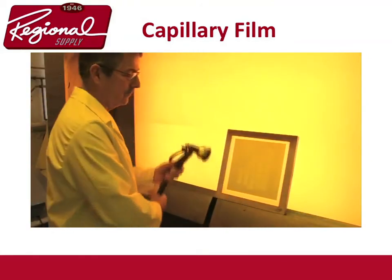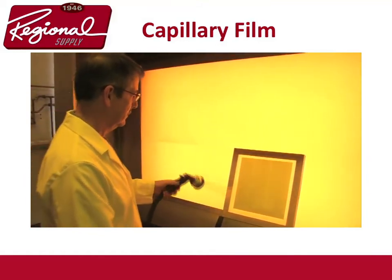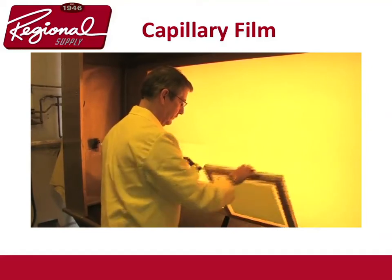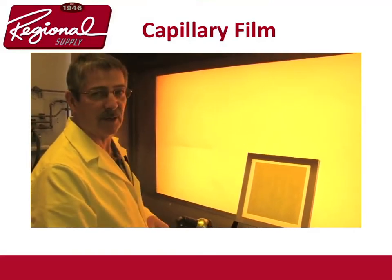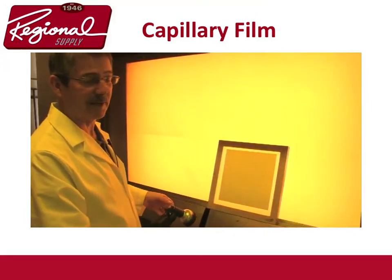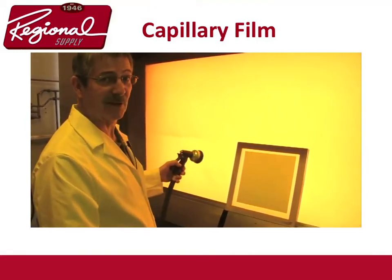Okay, I'm ready to go. Wet the screen down. Now you can wait 30 seconds to a minute to wash this out, but I like to wash it out right away. While this is developing, it's a good idea if you have a washout sink, make sure you have some good ventilation. It's always good to have good air with you.